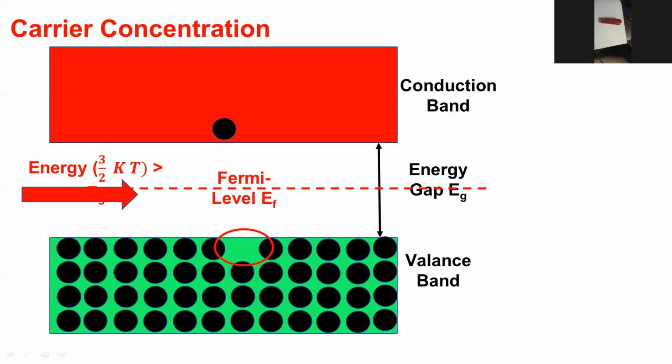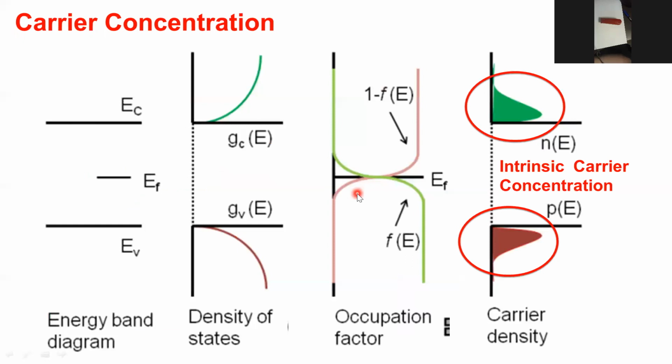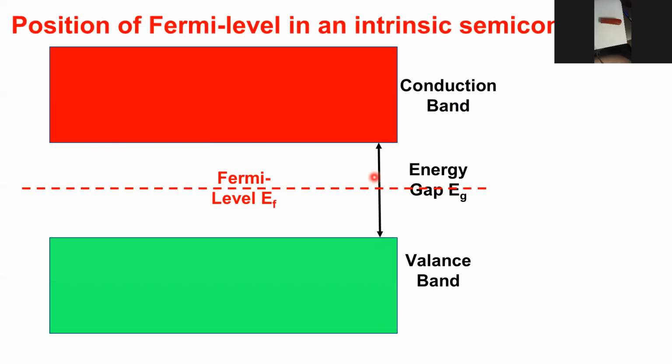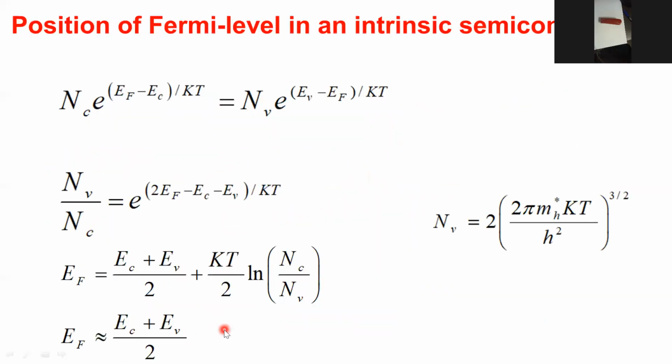However, for the Fermi level, we only know the mathematical meaning. We first say that the Fermi level is defined as the level at which the probability to find an electron equals the probability to find a hole, equals 50%. And then we have concluded a mathematical form for determining the position of the Fermi level. And we say that the Fermi level is located roughly in between the conduction band and the valence band, I mean in the center of the energy gap. It's not accurately in this place, but we can say that roughly it's there.